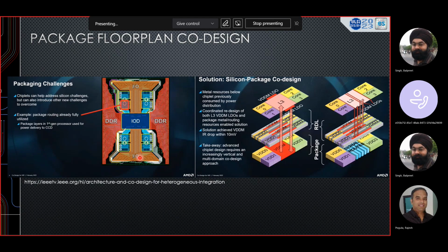Let's say you put a core there, it's a high power consuming IP, right? Then if you do the package traces right there, it's not going to really work out from the performance perspective, right? So that's why it's extremely important. It's a clear example of co-design importance, working with the floor plan, working with the package, working with the routability and all of the pieces together, power delivery, signal integrity, and power integrity, all those pieces together to make a product out of it.